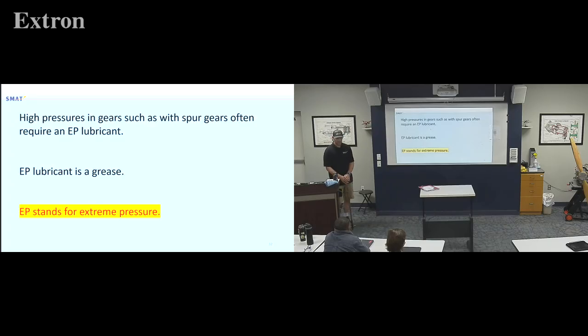So how about in the gear case of a PT6 engine up front? They're going to consider whatever oil's up front in there an EP lubricant. But really you just need to know, what's an EP lubricant? Extreme pressure. Something we're going to use typically for wiping friction.